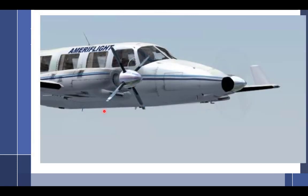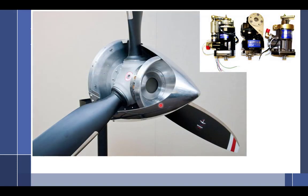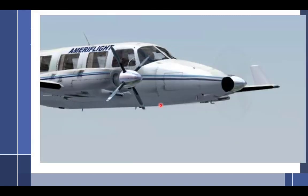I guess we can go one more. Feathering props. So constant speed, and then one step up is feathering. So if you notice, this engine's running. You can see the outline right there. And this engine is not running. And you can see that the blades are going right into the wind so that it's not windmilling. So constant speed feathering.